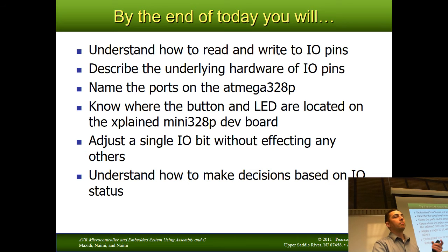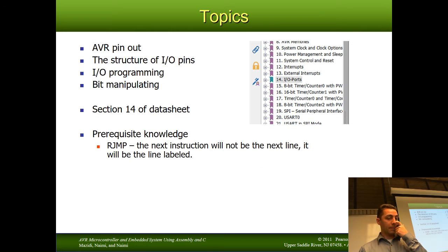You're going to know where the button and the LED are located on your development board and what port pins they connect to. You're going to know how to adjust just a single pin without adjusting any others. And you're going to be able to make decisions, simple decisions, based on I/O values. Okay. If you are looking for more information, if you look on the data sheet, there's section 14. I've got the PDF open here. It's all bookmarked. I/O ports is section 14 on the data sheet.